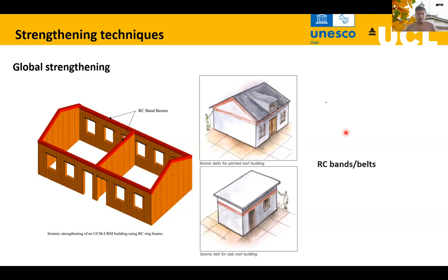It is quite hard to install these bands. In new constructions, these are very easy to incorporate, but in retrofitting, for example, in this first case here, we need to first remove the existing roof structure and then install these roof bands, and again reinstall the roof structure. But in older buildings, this also provides a chance to retrofit or strengthen, upgrade your roof structure itself. So it's a good thing.